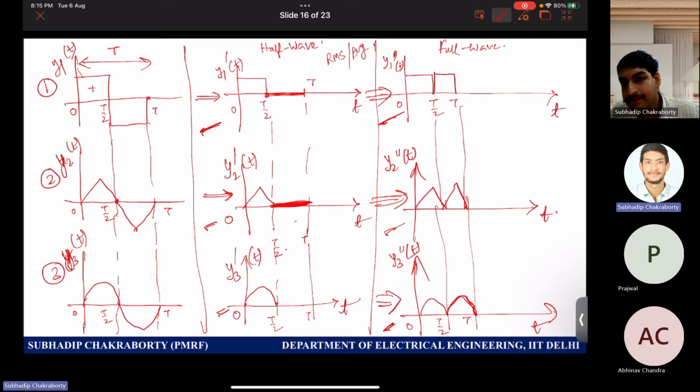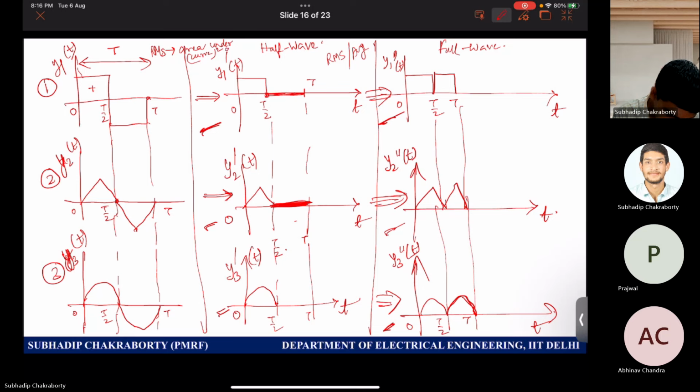And then you need to take the mean, similar to average, over one time period. But then you have another step. The final step, you need to do the square root of that total value. So RMS is nothing but the area under the curve squared, over T, and then you take the mean over T, and then you do a square root. So please note this.